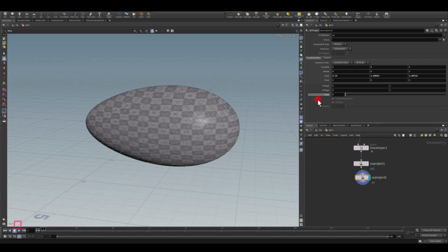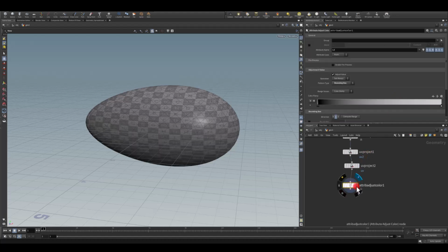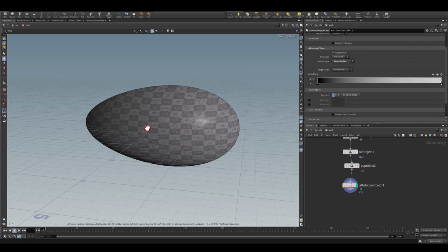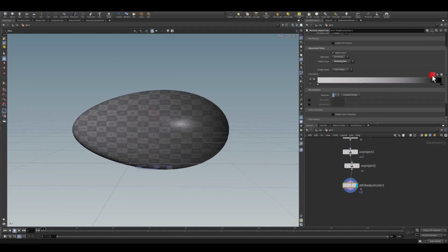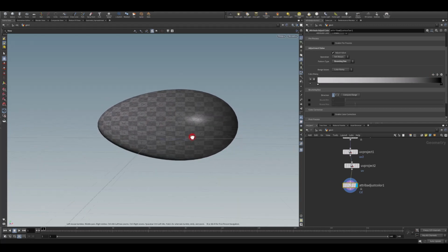Cool, so that's exactly what I want, and just making sure this is on UV0, which is the default UV in Houdini. Right, next I'm gonna apply some vertex color to it, so that will be color gradient. Color gradient is also one of the Side Effects Labs tools. I'm gonna select it, and as you can see, it's getting a weird axis. I actually want it on the x-axis like this, and I'm just gonna invert it, so the front or back, it depends how you're gonna put it in the